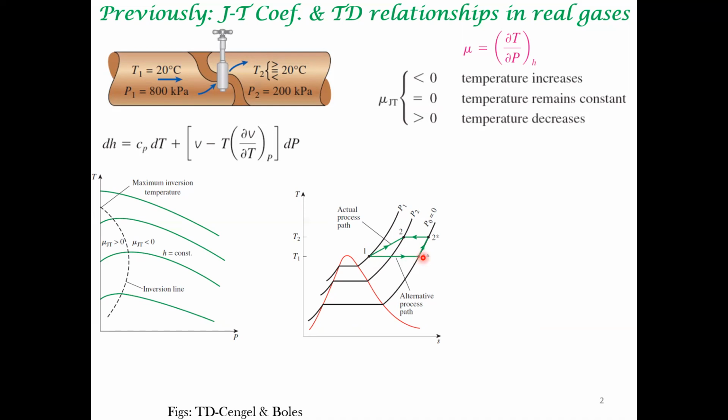We'll use such procedures for enthalpy changes, and then develop certain charts involving excess enthalpy, that is, how the enthalpy of the real gas differs from the enthalpy of an ideal gas at the same temperature. And we'd use the compressibility factor to tabulate such quantities.